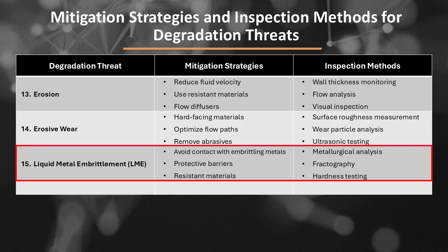Degradation threat number 15, liquid metal embrittlement or LME. Mitigation strategies for liquid metal embrittlement or LME may include avoid contact with embrittling metals, protective barriers, and resistant materials. Inspection methods for liquid metal embrittlement or LME may include metallurgical analysis, fractography, and hardness testing.